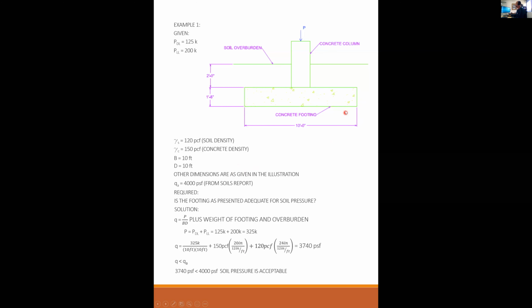It takes a big chunk of soil and shears across this face, and all that soil pounds up over here. So what you end up with is a big mound of soil over here and a foundation that is completely tilted. I mean, like 45 degrees, 50 degrees tilted.